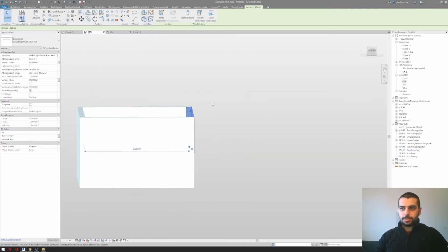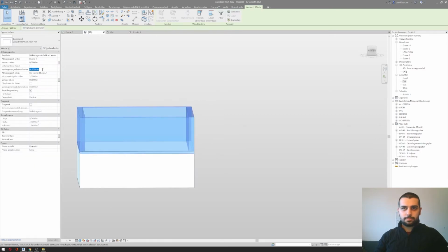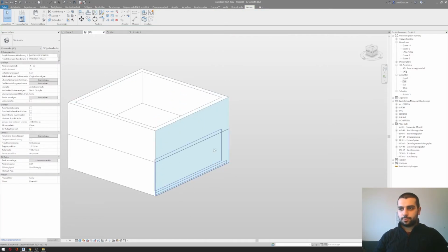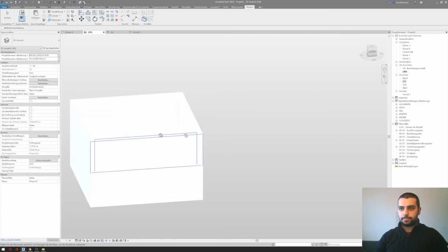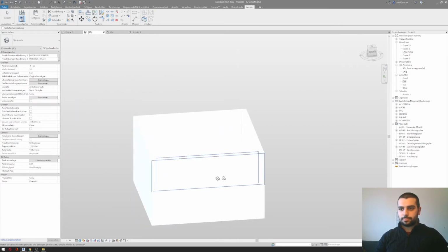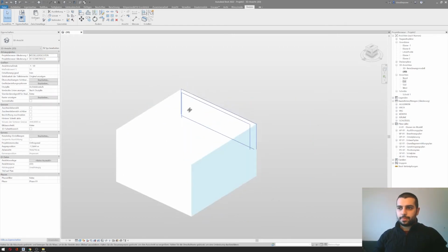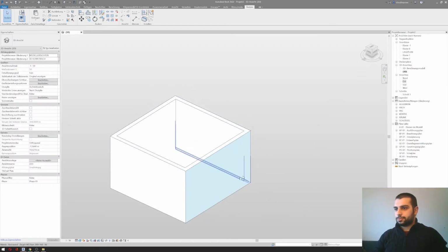What you can do is pick all the walls up here and make it 0 for this parameter. In this case, we only see one line, which we won't see if we connect them. Now I have my 2-floor high rooms.